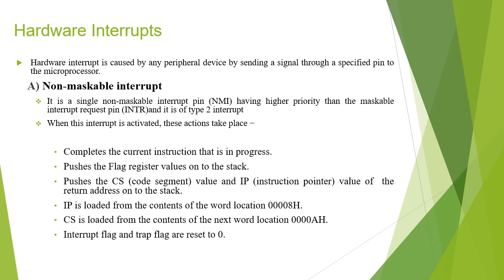So when you are receiving an interrupt through this NMI pin, the processor will complete the current instruction that is in progress, and after that it will soon pay attention to this NMI interrupt. That is, it will push the current values of your flag register onto the stack.